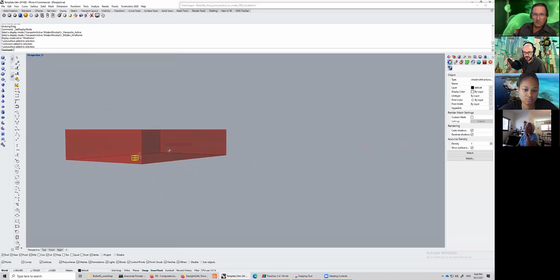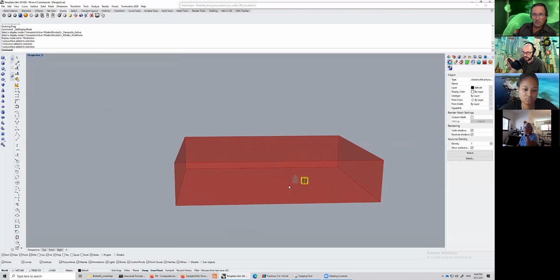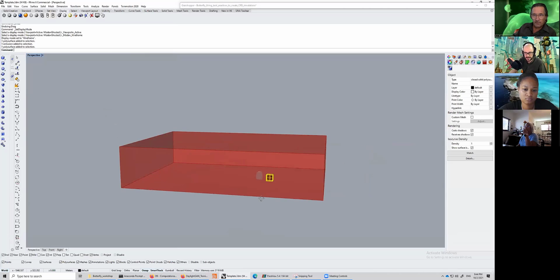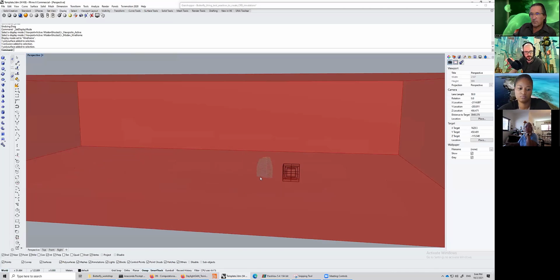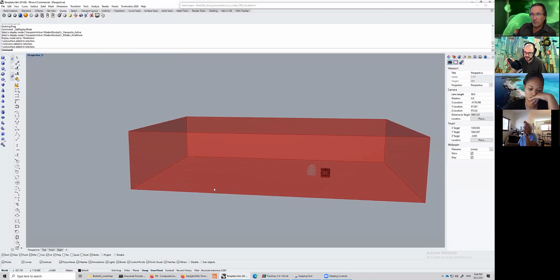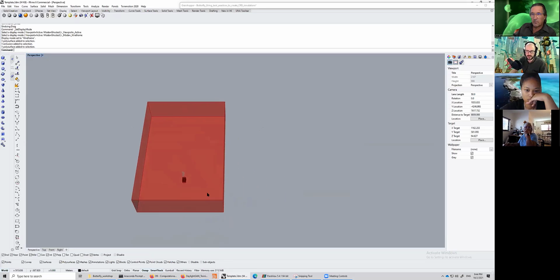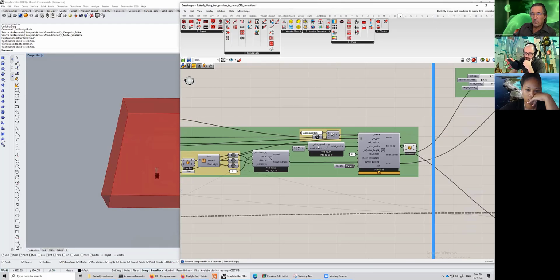So if I look at it this way, you can almost see how it's 5 times higher than the building, right? And in this case, we only have one building. That's why it looks a bit short. And in this case, this might be an edge case, although you will almost never have a simulation like this. You will always have context, right? But this could be an edge case in the sense that I think it might need more extension. Yeah, this is an intuition you will get after running studies, and you will see if they have converged or not. So, okay, this is how the wind tunnel happens.